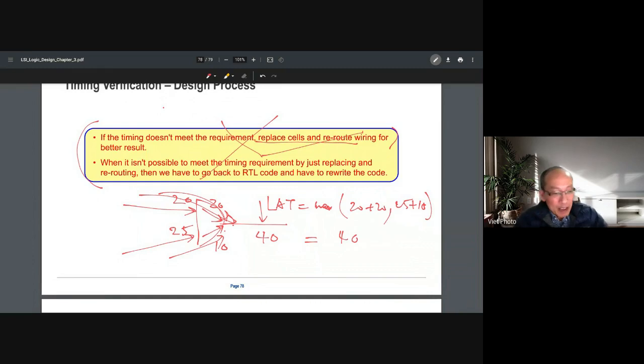Oh, for example, let's say you write the code, then we implement it and do the synthesis, and it doesn't meet the timing. We see that the logic depth on the timing path is about 20 levels. That means there will be 20 cells along the path.